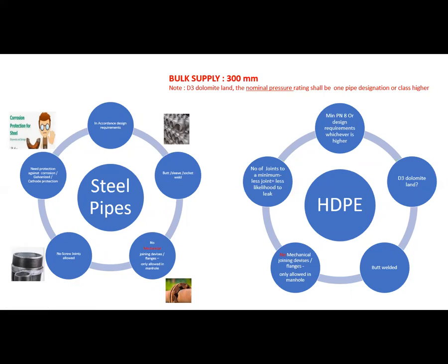And I just want to say that I have looked up the definition of manhole, and that's in SANS 10400P, and it does say a manhole or inspection chamber. So just check with your local council, if you're going to be doing those kind of joints, that it's allowed in an inspection chamber. And then remember, number of joints, please keep them to a minimum. The fewer joints, the less likelihood for it to leak.